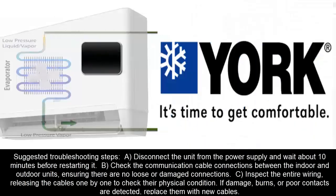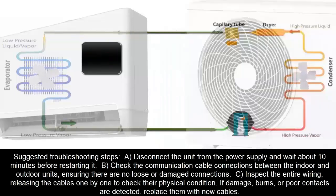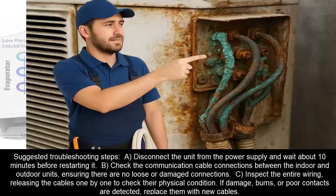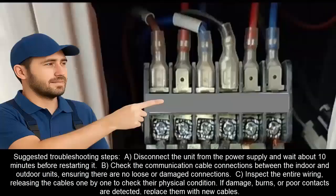Suggested troubleshooting steps: A. Disconnect the unit from the power supply and wait about 10 minutes before restarting it. B. Check the communication cable connections between the indoor and outdoor units, ensuring there are no loose or damaged connections. C. Inspect the entire wiring, releasing the cables one by one to check their physical condition. If damage, burns, or poor contacts are detected, replace them with new cables.